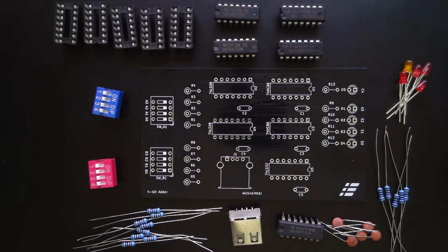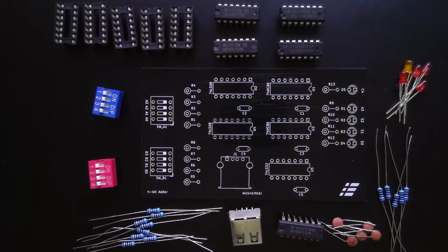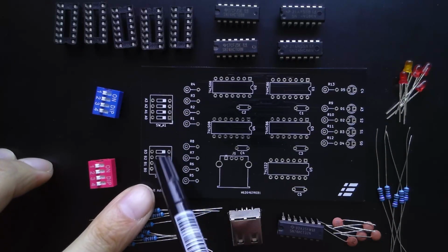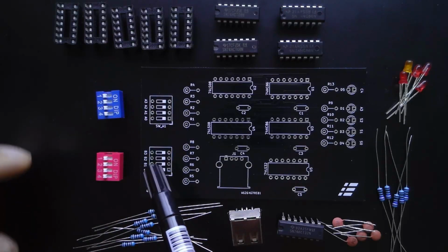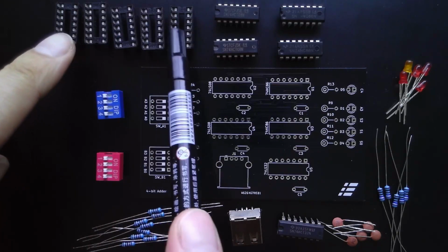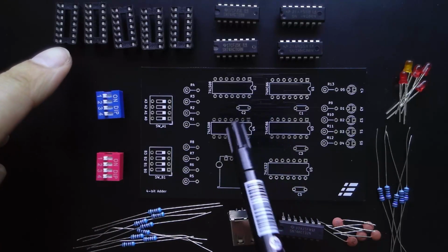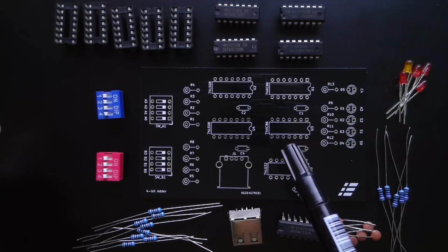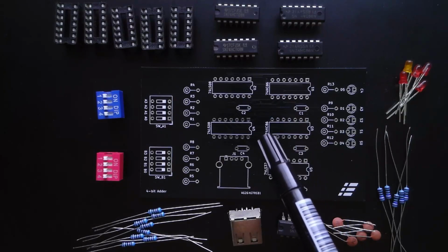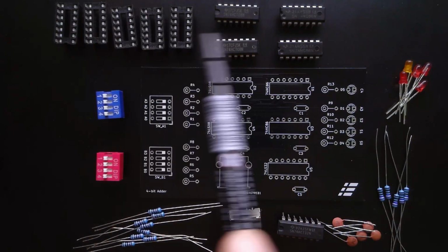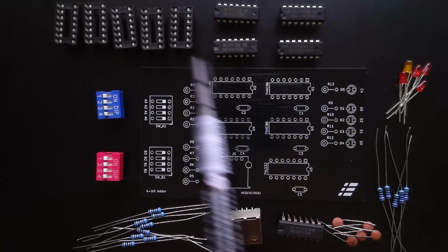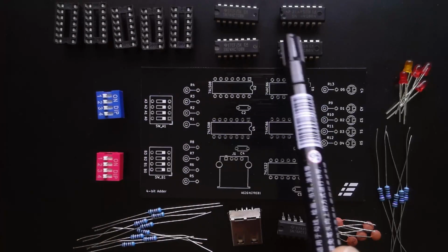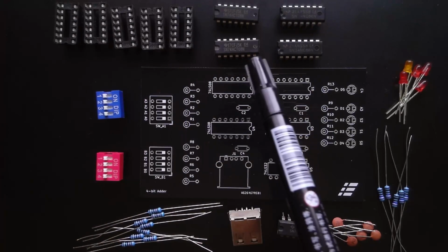Our printed circuit board has arrived along with all of the components. So let's just check we've got everything here. The 2 switches here, we have our dip switches. I've also got all of these sockets, and I'll solder the sockets in, and that way if I make a mistake or I need to remove something, I'm only damaging sockets, and it will save the integrated circuits on these chips. So I'll solder those in and then I can just plug these guys in to the sockets.